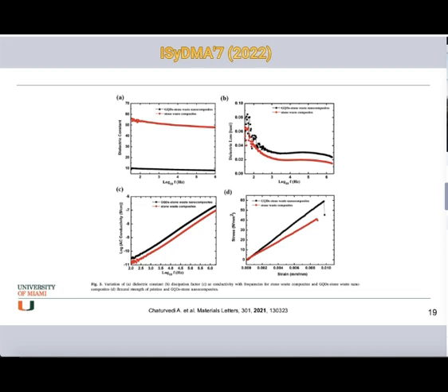So figure D is linked to the flexural strength curve. The pristine stone composite shows a strength of 40 megapascal, whereas the carbon dust reinforced stone nanocomposite exhibits a flexural strength of 60 megapascal, compared to the pristine epoxy at about 33 megapascal.